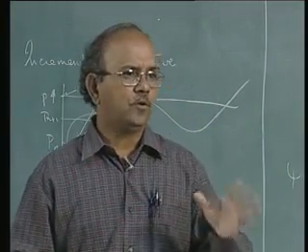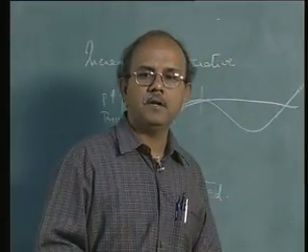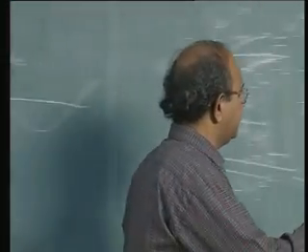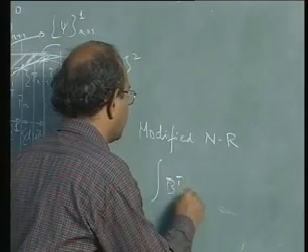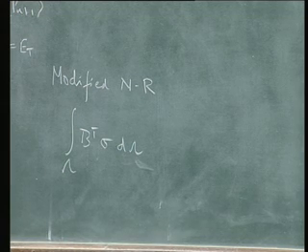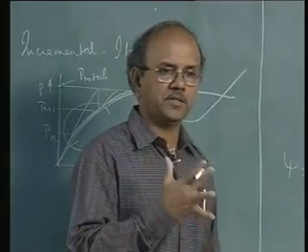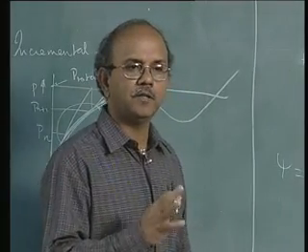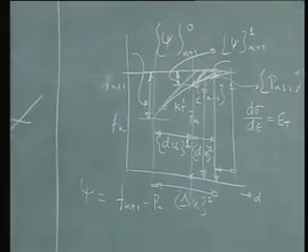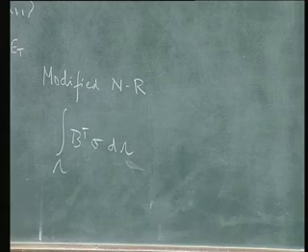Fine. So before we go further, let us do a problem, and before even that, let us look at our internal forces more carefully. Remember that I said the internal force is written as the integral of B transpose sigma d omega, or dV. And though I am not going to give a very rigorous definition, or do virtual work, I just want to indicate a small thing before I go further and consolidate the whole procedure by doing a numerical problem. Now look at that B transpose sigma. This is what is called P.